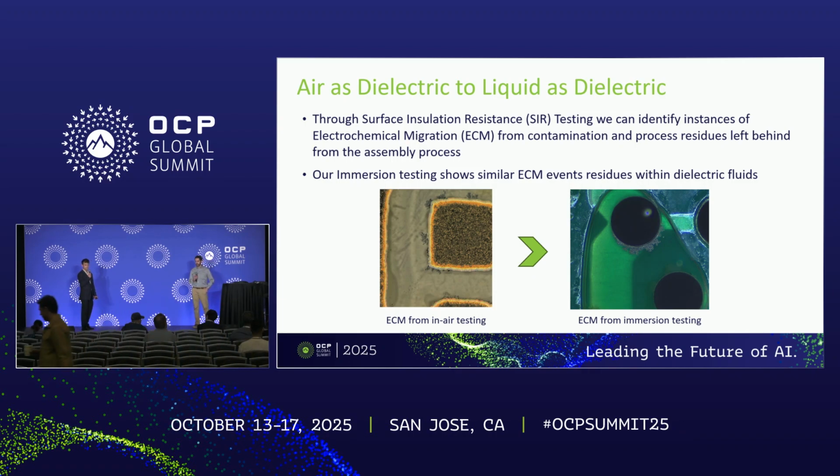coolants. To take these images, we utilized faux components made of borosilicate glass that had copper pads screened onto them, that allowed us to mount them on our PCB coupons in a manner that resembles hardware assembly. You can see the metallic filaments growing between the conductors of opposite polarity in both examples. In air, this is made possible through electrical bias, humidity, and process contamination. But as mentioned, in two-phase fluid, there is the added potential for contaminant building up over time. And we call this global contamination.